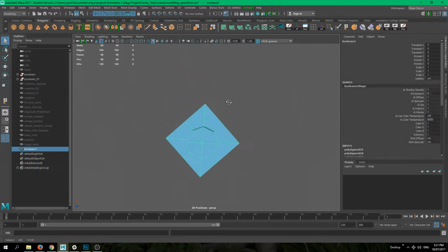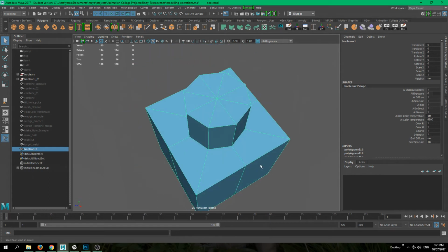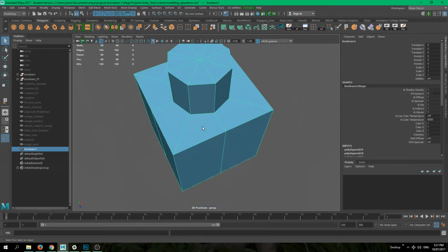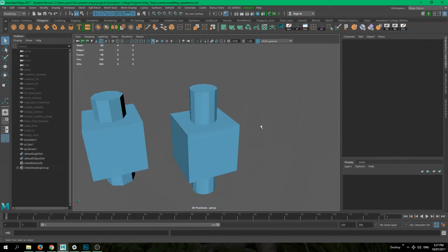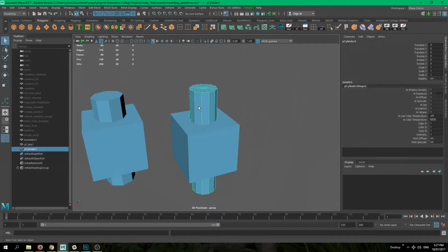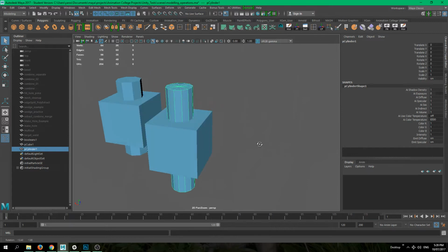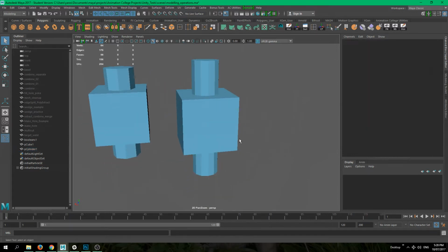And so, as you can see now, the mesh is properly connected. We don't have any n-gons. Everything is actually a proper polygon, which is quite cool. So I've just created another set of objects to show you another Boolean operation. So we just have this cube and cylinder again. My cylinder, I think, has 12 faces going around. Still quite a small number, which is good.